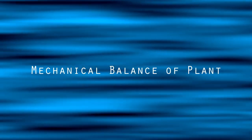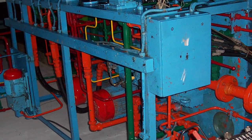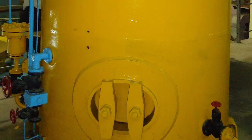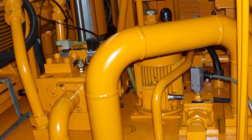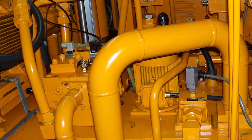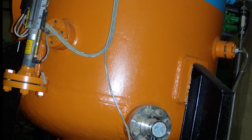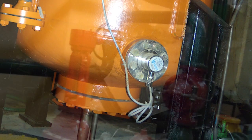Mechanical balance of plant. Hydraulic control system. Oil pumping unit. A system used for transmission and control of forces and movements by means of hydraulic fluid. It is needed for turbine regulation, operation of brake, MIV, BFV, turbine guide vanes, seal control system, etc.